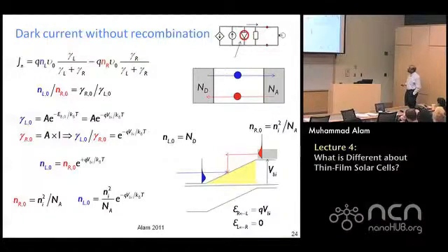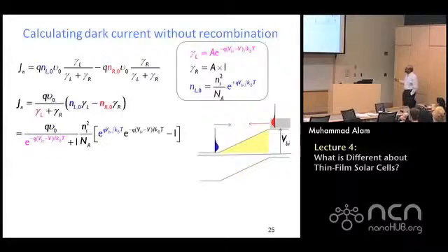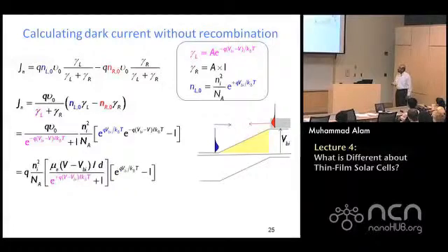Now, once you insert these equations, again, gamma R and gamma L is the same, you insert this equation under bias condition. In that case, this will remain the same, the gamma L naught, N L naught, so you take this expression in, and the gamma L, now the barrier is a little smaller because you have applied a bias, and it is smaller by V, VBI minus V, because by applying a voltage V, this has been suppressed, so you do a few lines of algebra, and you get an expression here.